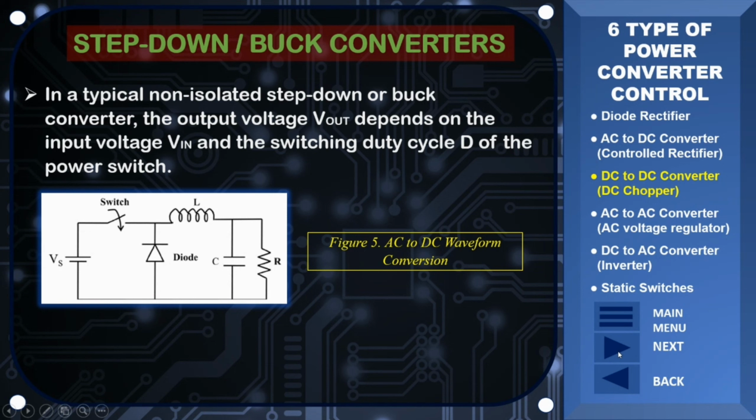To reduce voltage ripple, filters made of capacitors, sometimes in combination with inductors, are normally added to such converters' output, load side filter, and input, supply side filter. Its name derives from the inductor that bucks, or opposes, the supply voltage.